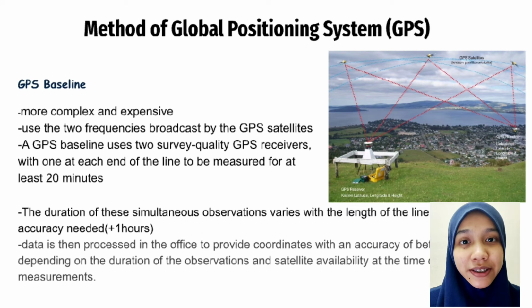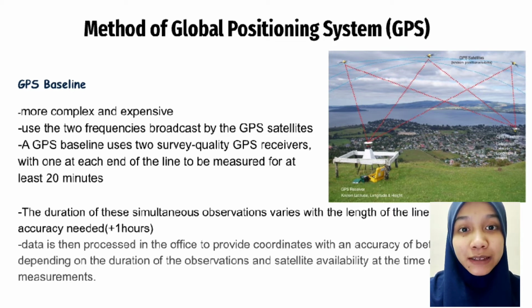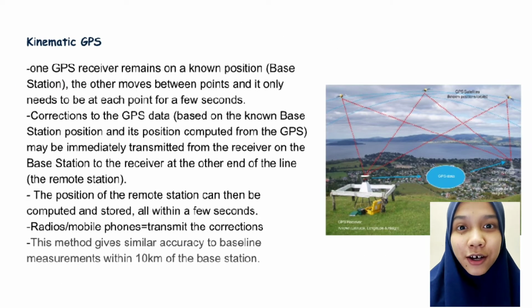The first one being the GPS baseline. So what is GPS baseline? Well, it is actually more expensive and more complex than other methods of using GPS. The reason is that it uses 2 frequencies broadcast by GPS satellite, and the baseline uses 2 survey quality GPS receivers, with one of them being at the end of the line to be measured for at least 20 minutes.